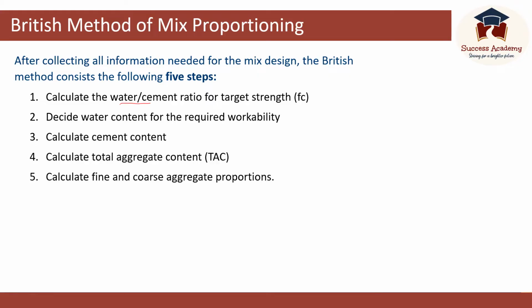Calculate the water to cement ratio for the targeted strength. Decide water content for the required workability. Calculate cement content. Calculate total aggregate content and calculate fine and coarse aggregate proportions. Now let's see these steps in detail.